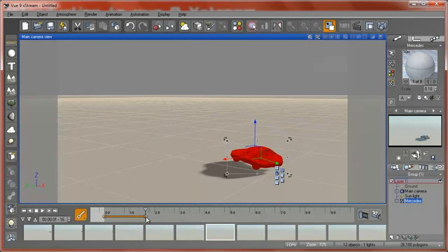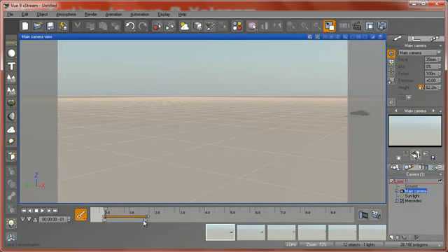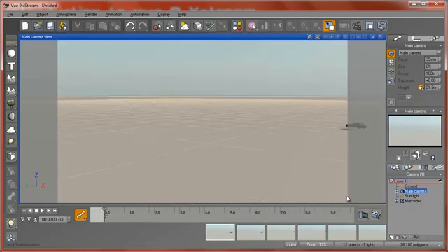Okay, for example, I'm gonna just go back here. Here is the time of your animation. So for example, I'm gonna go to 0. Here we have actually our main camera which has been animated, so I'm gonna delete it, go to time 0 and move my camera.